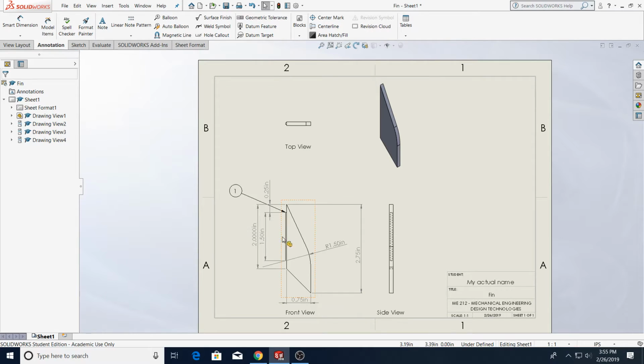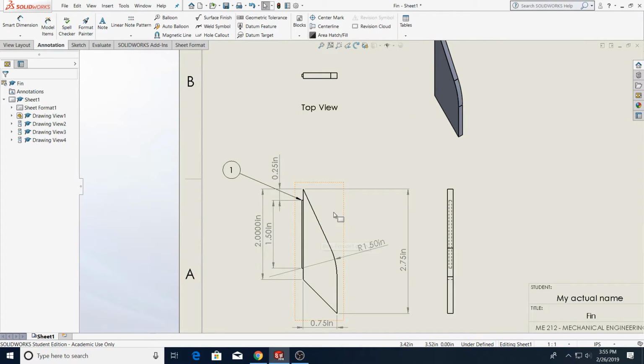Or you could say something like, hey, this notch needs to be able to actually nest inside the fuselage and should not have any wiggle room at all. You could make those call outs by using a balloon. The balloon is also really useful for creating notes on assemblies to indicate a bill of materials.